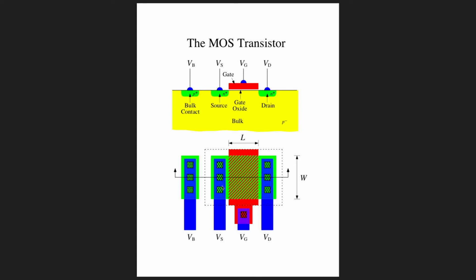Well, with a MOSFET, the structure is symmetric. The source and the drain regions are basically at the same doping level, and usually the device is physically symmetric. We can actually make devices that are asymmetric if we want, by the geometry that we impose on the device. But most devices are rectangular and physically symmetric.